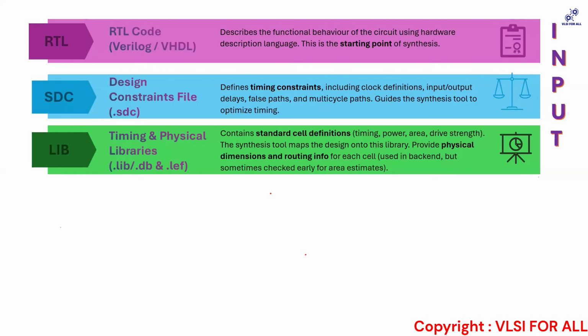These are the kind of constraints you can give it. But when you're doing a synthesis, you are not allowed to restrict a lot of things at the synthesis end. You can restrict it at the PNR end based on your project to project experience. You get it like, okay, this cell is not useful for my design.